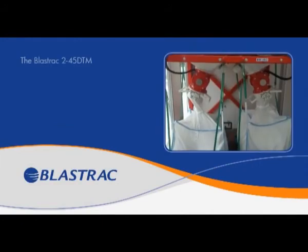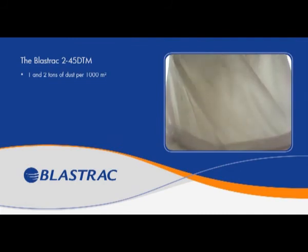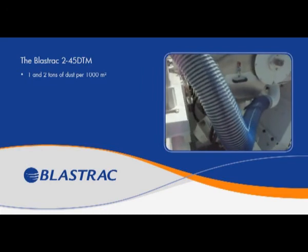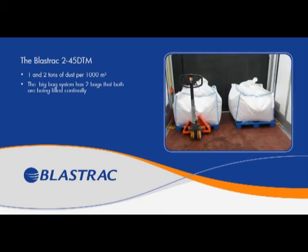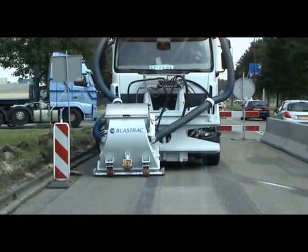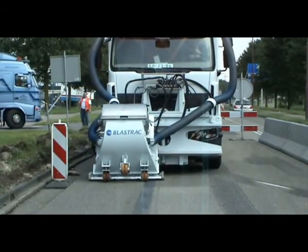During the job, a lot of dust will be generated. Depending on the surface to be treated, it can vary between 1 and 2 tons of dust per 1,000 square meters of road surface area processed. Our new big bag system has 2 big bags that are both being filled continually. This system allows you to change each individual full big bag during operation for an empty one without any leakage of dust out of the system. So there is no downtime due to dust handling.